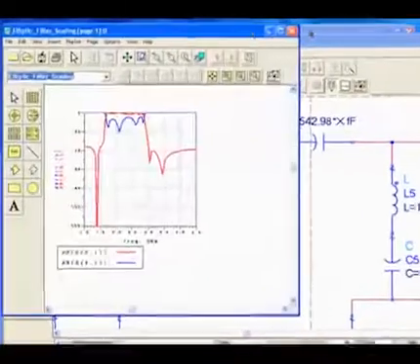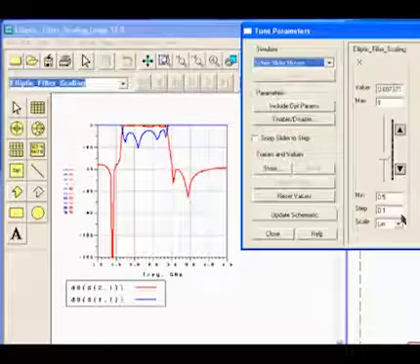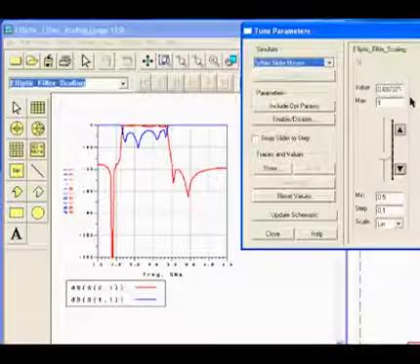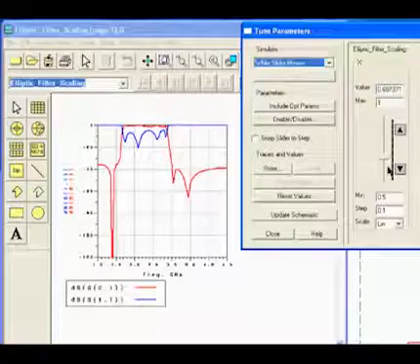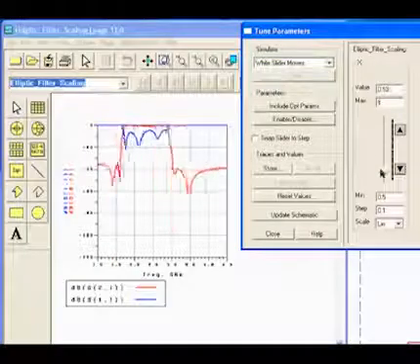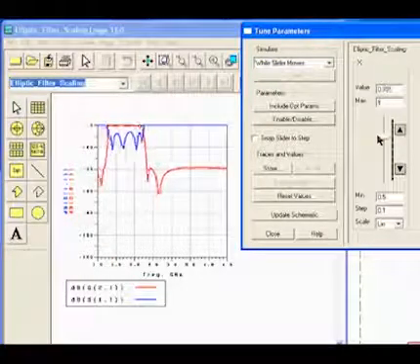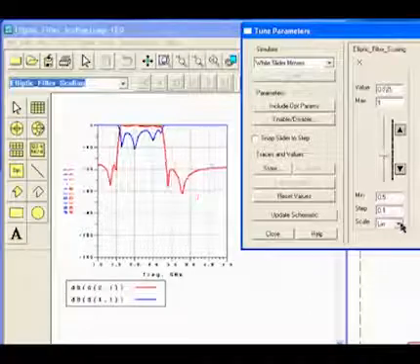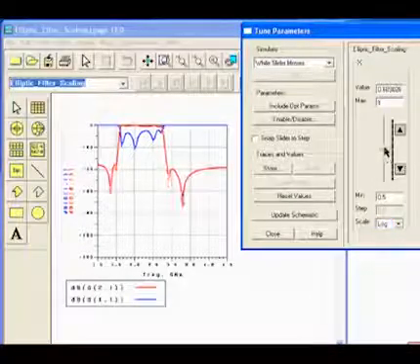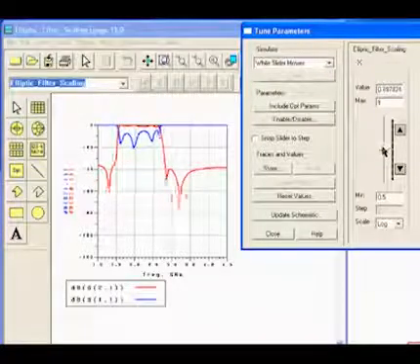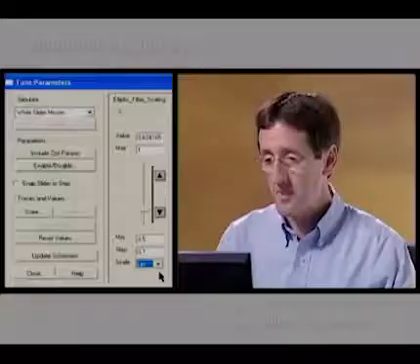This is the new tuning user interface here. The step size, minimum, maximum, and current values of X are shown in these boxes. As I move the slider, the circuit performance updates in real time. We are tuning with 80 frequency points and can sweep linearly or logarithmically. Having the choice of a linear or logarithmic sweep can make it easier to tune rapidly changing circuits.